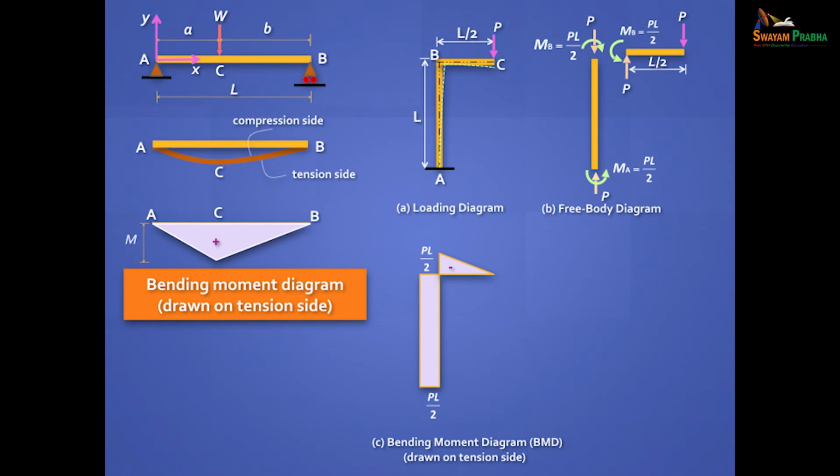Now, if you have tension at the top corner here on this beam, you're bound to have it at the same corner in this element. Right? And so if you need to put reinforcement in this reinforced concrete column, your steel is really needed at the top here and on the left side here. The same bar can go right through. Are you getting it? So one look at this diagram and I know where to put my steel if it's reinforced concrete. Got it? So this is how you draw the bending moment diagram on the tension side.